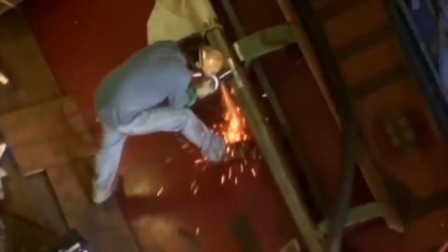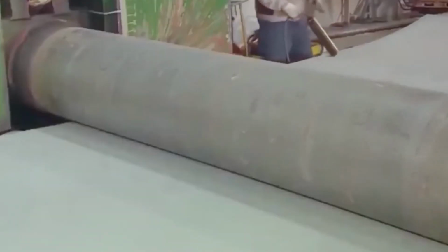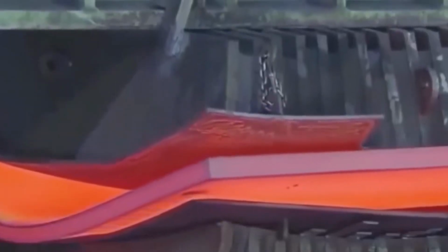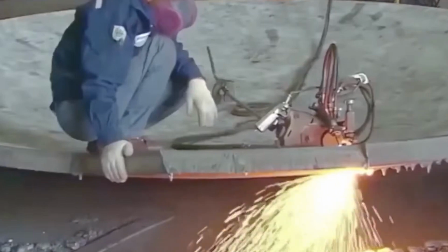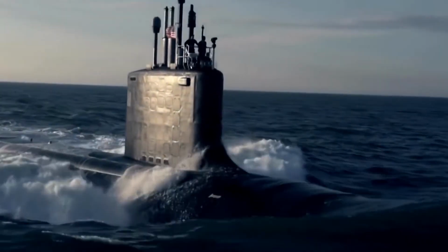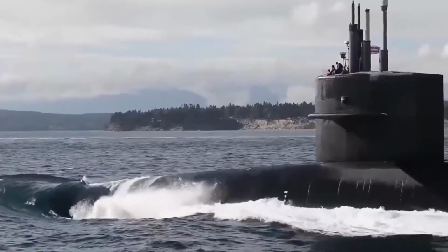To begin, acetylene torches are used to cut the steel plates into the specifications that are wanted. Afterwards, rollers of industrial grade are used to bend them into the desired shape. A wooden template that depicts the shape of the hull is then used to guide the placement of the plates around the template. In order to create an inner hull, the plates are welded together after they've been positioned. This procedure is repeated for the outer hull, and spaces are left between the hulls to accommodate the ballast tanks, which are essential components of a submarine.